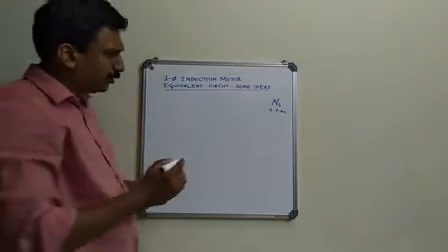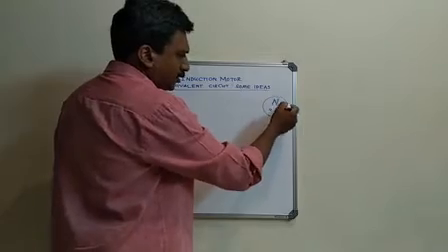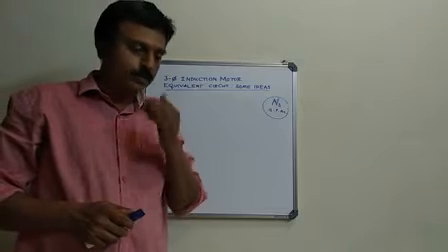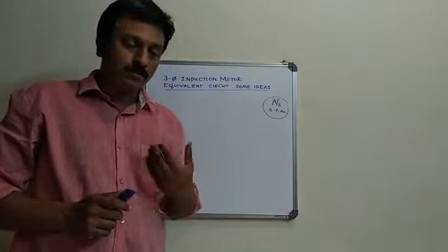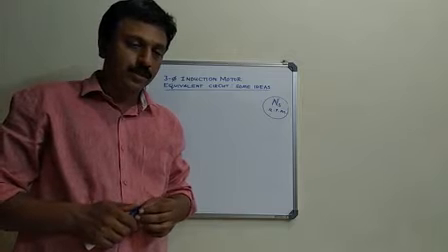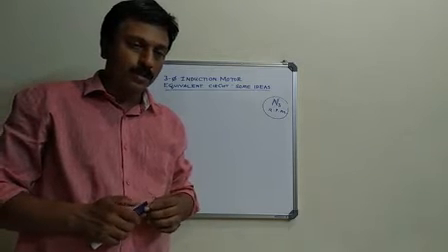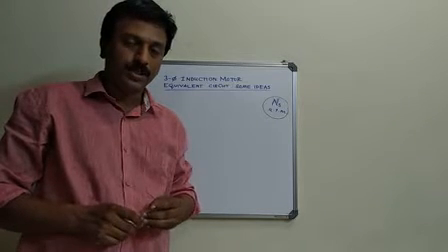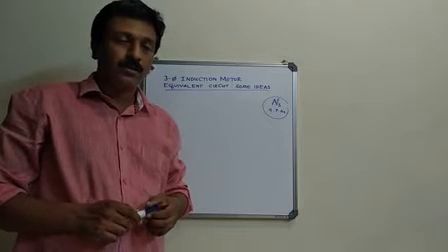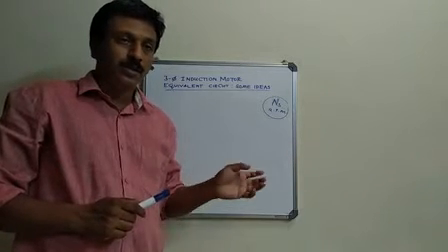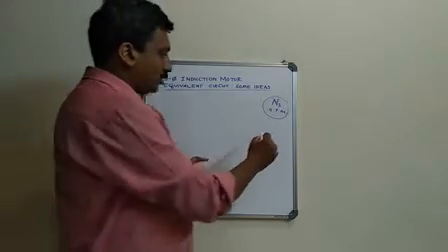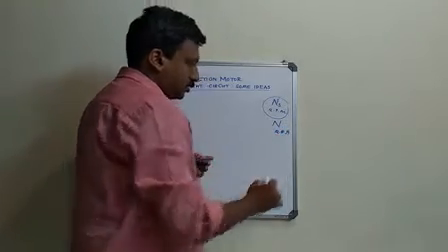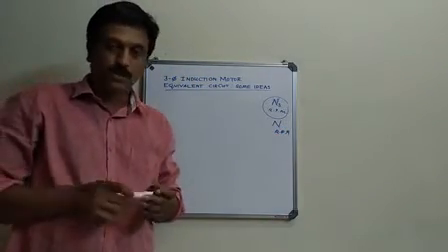The rotor tries to attain this speed, but it is not able to, because if it did, the induced EMF would become zero and the torque would vanish. So losses and frictional effects retard the rotor, and it settles down to a speed usually denoted as N RPM, which is subsynchronous, lesser than the synchronous speed.